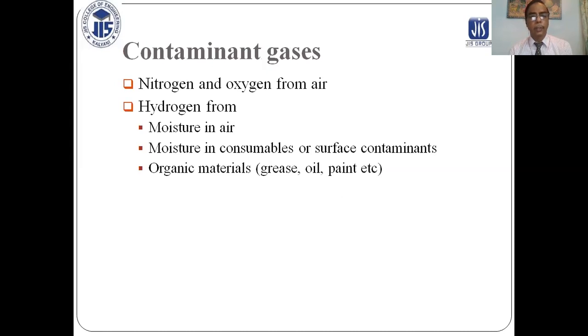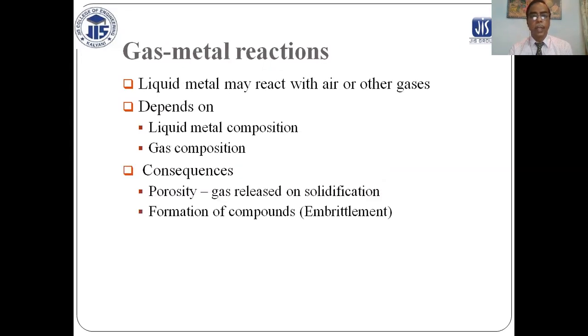Contaminant gases: nitrogen and oxygen from the air, hydrogen from moisture in the air, moisture in the consumables, or surface contaminants such as organic materials, grease, oil, and paints. Gas-metal reactions: liquid metal may react with air or other gases, depending on the liquid metal composition and gas composition. Consequences are porosity, gas release on solidification, formation of compounds, and embrittlement.